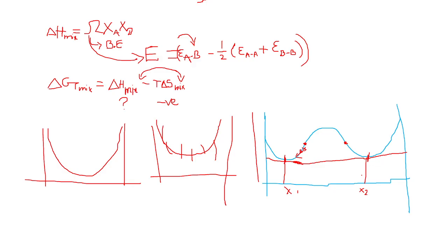So again, the next part is the growth part. The growth part depends upon the diffusion of atoms, if you are talking about the diffusional phase transformations, right? Even in diffusionless phase transformations, we need to have a collective movement of atomic planes. So it's more like a pack of cards moving, right? So that's what we see in martensitic phase transformation, right? There is no diffusion of atoms, but there is a collective movement of atomic planes.